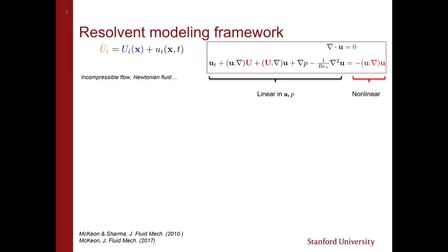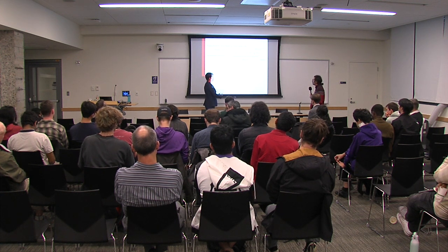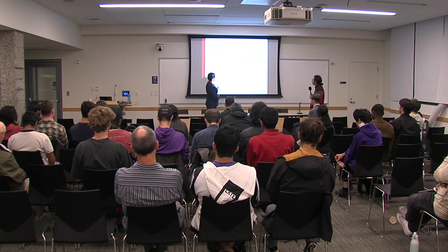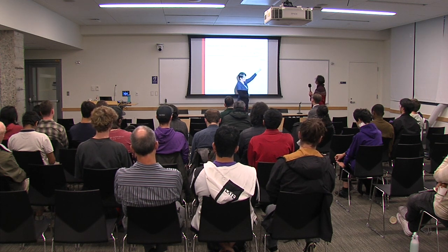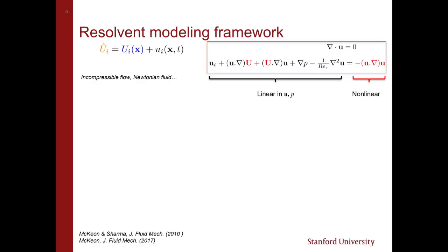However, people have tried to find the optimal eddy viscosity to capture the behavior of flows in the fewest resolvent modes, right? So that's a very legitimate way to think about the efficiency of the basis set when you take a data set and you project it onto the basis. So trying to reduce the number of functions that you need. That's a good way to do it. The reason we don't do that here is because any time I mess with this forcing, all of these resonances and the simplification on the nonlinearity I was showing you goes away, right? Anything that's left over here is extremely complicated and very hard to interpret. So because we're interested in compressing the nonlinear term and improving that modeling, we keep it. But there's everything in between, right?